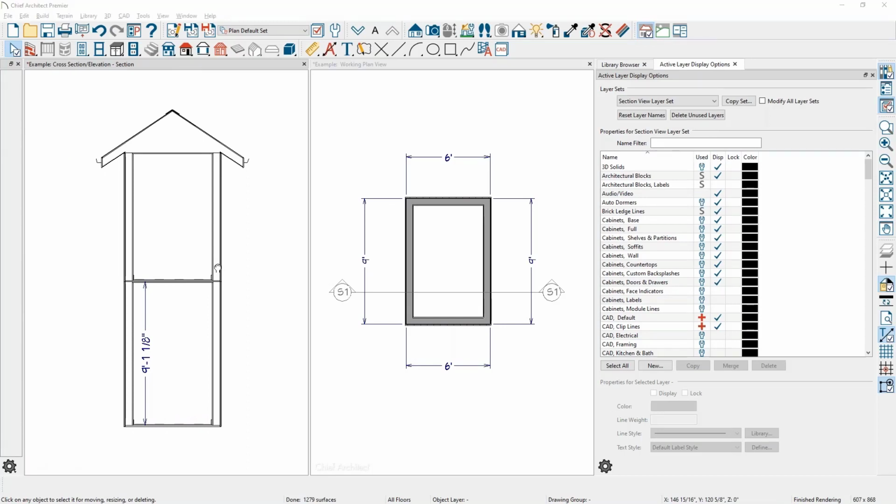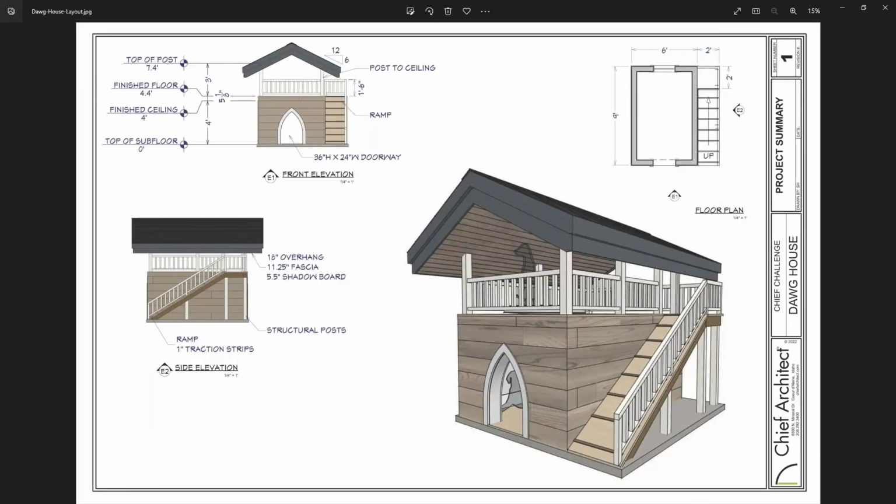Thanks, Scott. We had another write-in question. How did you set the ramp so that it lands at the top floor? Yeah, so when you look at the ramp here, ramps typically, if they're going to meet ADA standards, might be a 1 in 12 pitch. And clearly this is very steep.